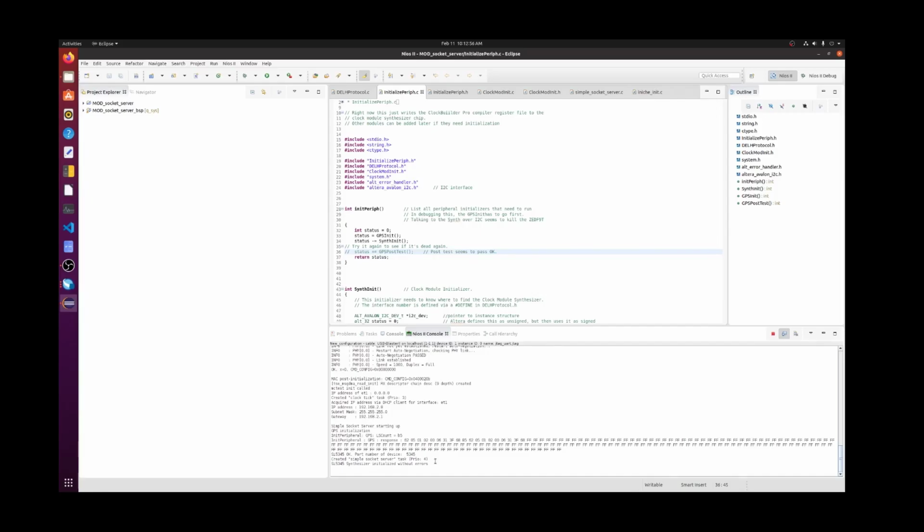The GPS module is up, providing the correct frequency. There is a 10 megahertz output available on a small connector on the data engine adapter board, and it's providing 122.88 megahertz to the receiver module and the FPGA on the board. In part 3, we'll go look at using the Python command line interface to bring up a protocol handler so we can investigate some properties.